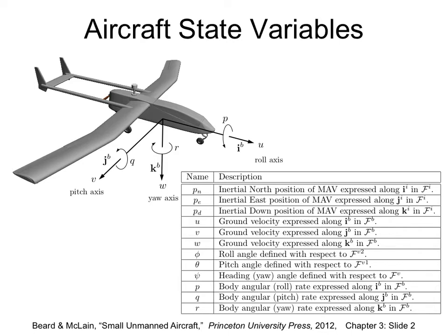So is it just like the inertial frame? It's body frame. Body frame. So how fast the vehicle is moving in its nose's direction, in forward direction. So that's U. And when the vehicle is moving this side, it's V. It does not have any connection, because in inertial it will depend on what your attitude is. If UVW is known and you know the attitude, you can tell what Pn dot, Pe dot, Pd dot are, and you will use UVW to compute them. That's how we will get it. But yes, that's the body frame velocity.